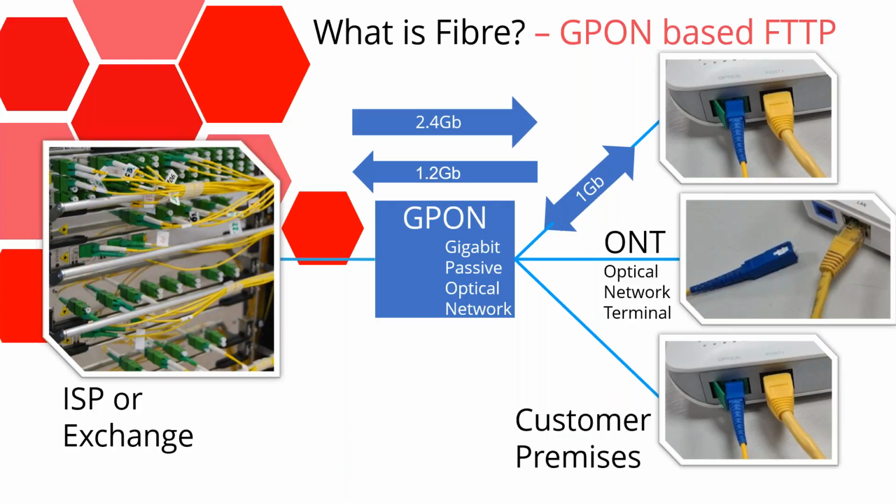Each ONT gets a time slot to send data, giving around 1.2 gigabits per second upstream bandwidth for all connected lines. The endpoint link received at the premises is 1 gigabit up and down, but this is shared between other points on the main fiber. The line's data rate would also be set based on the package that the subscriber has paid for.